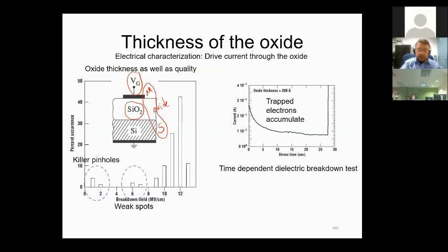You try to drive this oxide by applying voltage from the top, from the gate side, okay? Since this oxide is very thin, and I would like to remind you the electric field is equal to, actually, I won't write the derivative form, but I will say simply voltage across this whole oxide over the thickness of the oxide. Let's call it T. Of course, since these thicknesses are in terms of nanometers or so, the electric field that you will build up will be really large, even as low as you apply like a few volts here, okay?